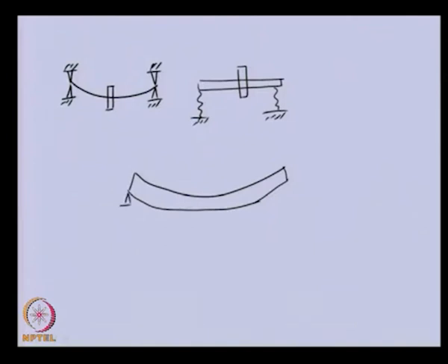So, when we mount them on bearings, they not only have an appreciable amount of inertia, they also have elasticity. For such rotors, we cannot distinguish where a particular mass should be concentrated, at one location or several locations. So, generally in this case the elastic property and the mass property of the shaft we need to consider continuously.